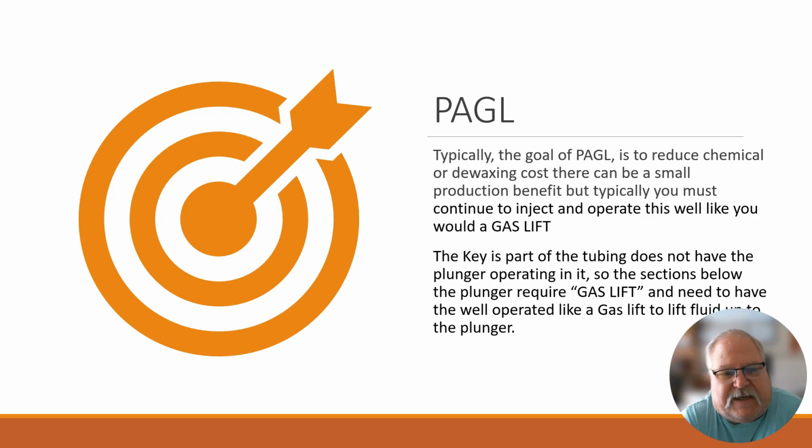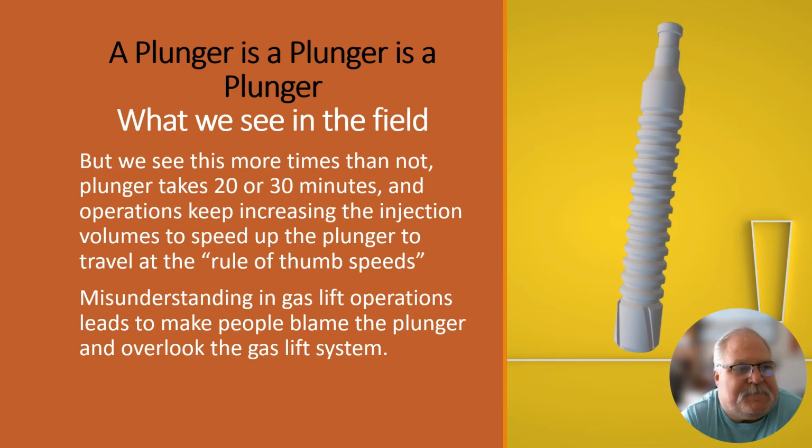Usually people that are running PAGL are trying to reduce chemical dewaxing costs. There can be small production benefits, but typically you must, again, continue to inject and operate it like you would a gas lift. So I think I've beaten that up enough. A plunger is a plunger is a plunger.